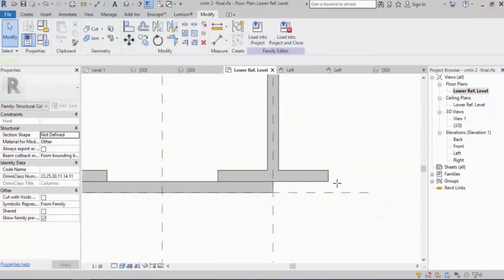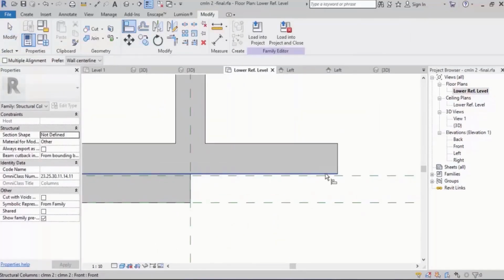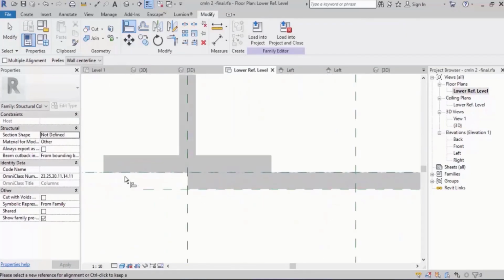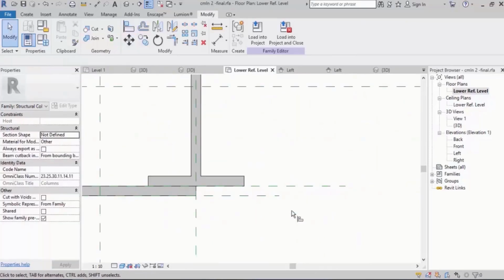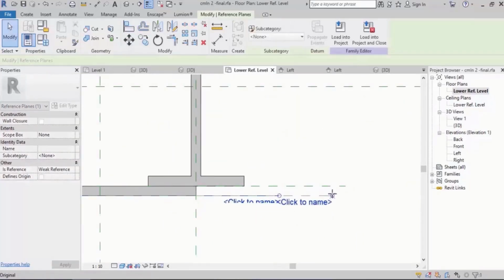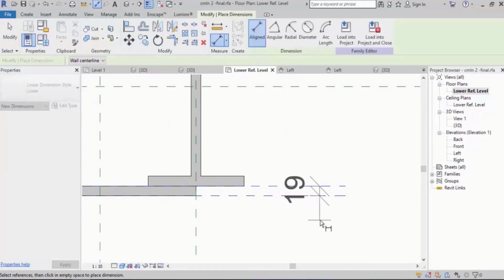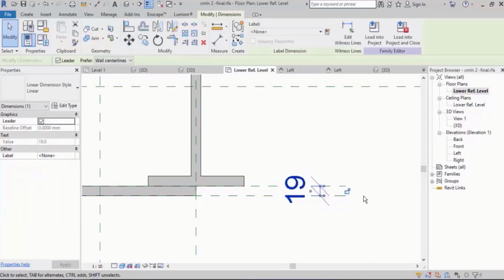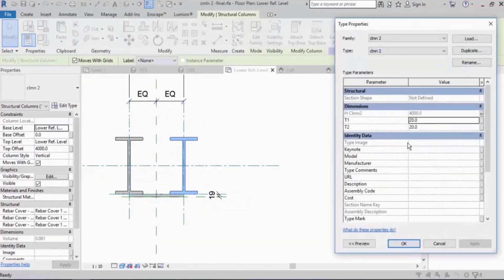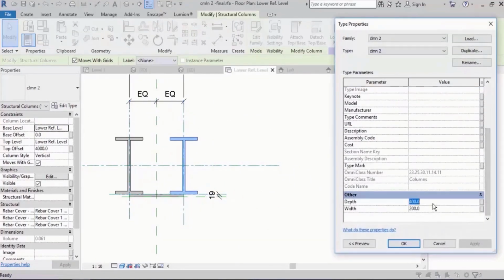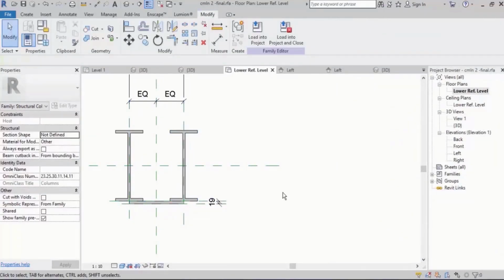And it's not bad to draw a reference plane here for the lower part of them. Lock. I could have not drawn it, but I sometimes say that if you want to measure the subjects, connect a RP to them. Now, this dimension is not parametric, it's just locked. So, for example, if the size of this changes, if it becomes 50, this will change, will be moved.